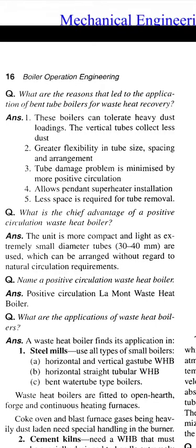The vertical tubes collect less dust. Greater flexibility in tube size, spacing and arrangement. Tube damage problem is minimized by more positive circulation. Allow pendant superheater installation. Less space is required for the tube removal.